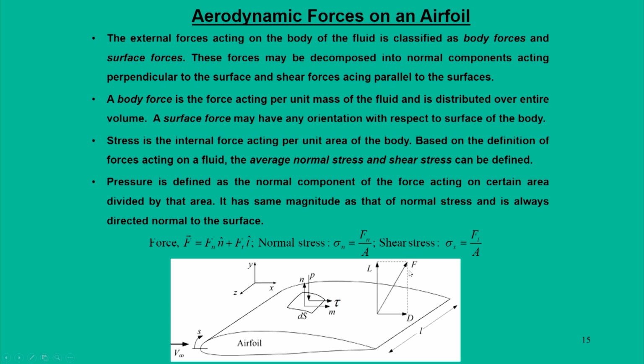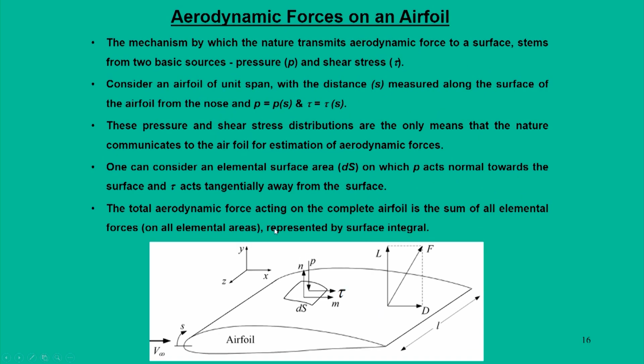And when you decompose this resultant force along the direction of the motion of the free stream, we call this drag, and perpendicular to this drag is called lift. So, the basic summary is that when an airfoil experiences a pressure difference at its upper and lower surface, it experiences lift and drag. These things are quantified through mechanics principles, and they are termed lift and drag.